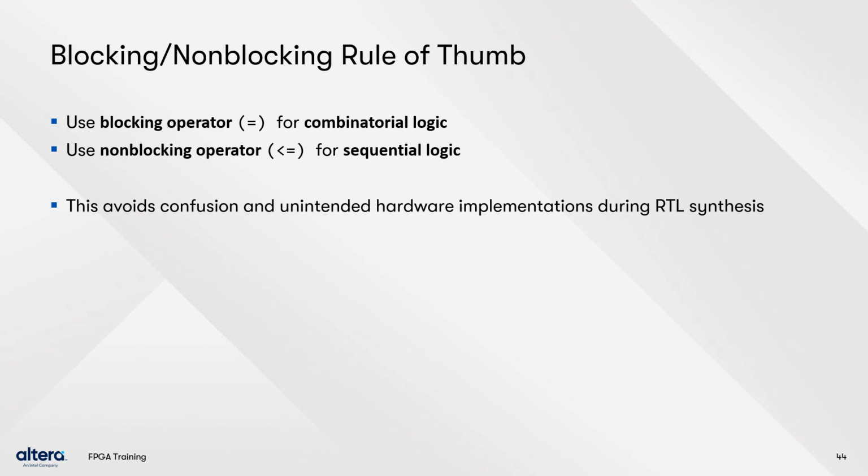A good rule of thumb to follow is always use blocking operators for combinatorial logic and non-blocking operators for sequential logic. These will avoid confusion and improve the readability of your code.